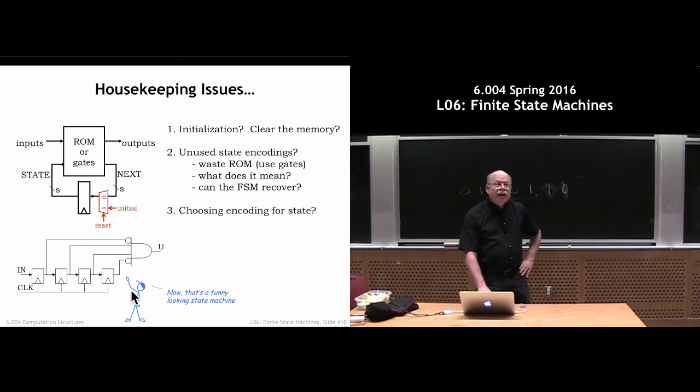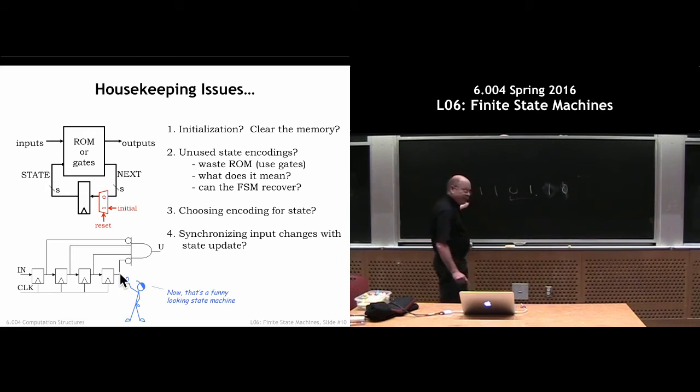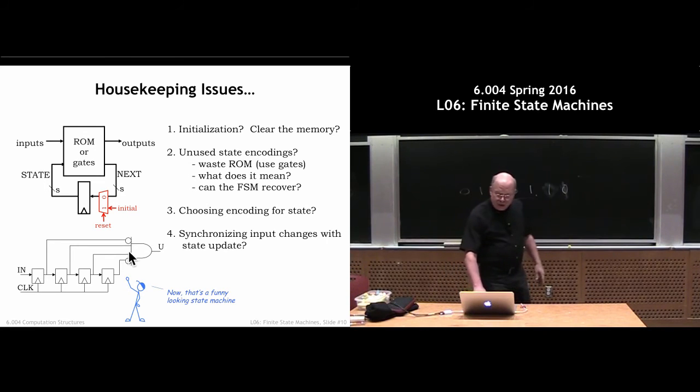And what I've done is come up with a simple way of remembering what the input values were, and here I built a very simple piece of combinational logic that says, oh, look, if the last values were 0, 1, 1, 0, going backwards in time, so 0, 1, 1, 0, if that's true, then unlock the lock. So there are times when you can pick a way of remembering the state.